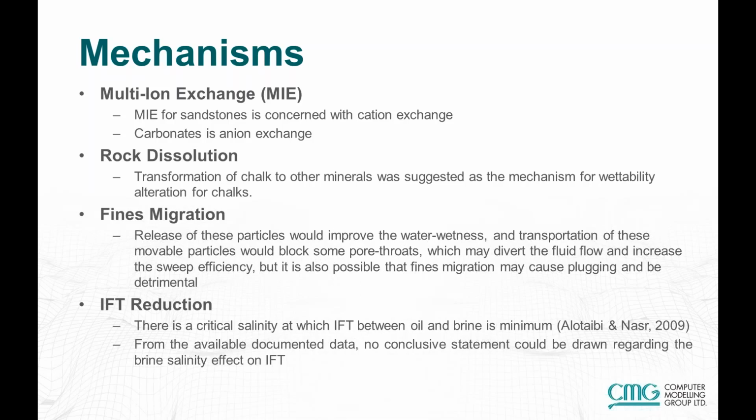Fines migration may be important. The release of these particles would improve the water wetness, and then the subsequent transportation of these particles would block some pore throats that may divert the fluid flow and increase the sweep efficiency, but it's also possible that the fines may cause plugging and be detrimental. Interfacial tension reduction effects may be important. There's a crucial salinity at which IFT between oil and water is minimum, but from the available literature to date, there's really no conclusions that can be drawn whether IFT is important or not for this process.